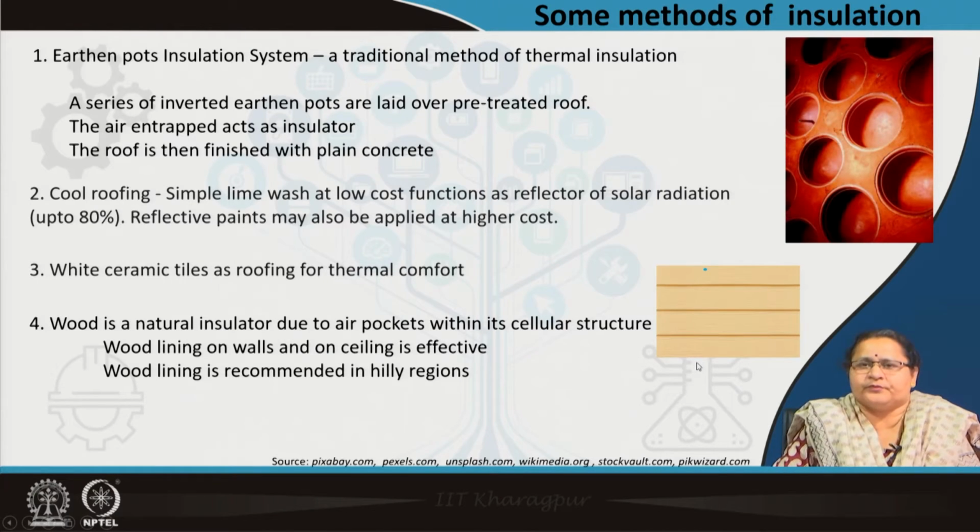Coming to wood, as I have told, trapped moisture and trapped air within glass fiber, steel, glass fiber, rock fiber, mineral wool, glass wool is the crux of thermal insulation. Wood is also a natural fiber, where, due to the removal of moisture, air pockets are formed, a very small cellular structure.